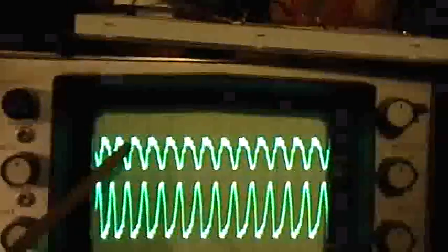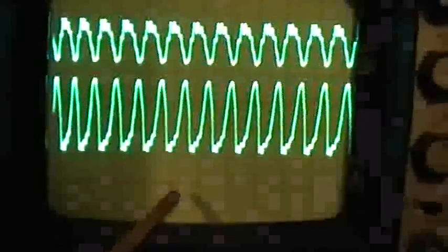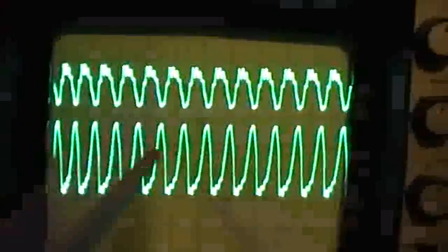The current viewing resistor is being displayed at 1 volt per division. And the battery trace is being displayed at 20 volts per division, and its baseline is there. So we have 20, 40, and then whatever peaks are there. So the midline of 48.8 volts is shown. Right now we've got about 140, 150 milliamps flowing through the system, and we are heating the load. That load is getting warmer.